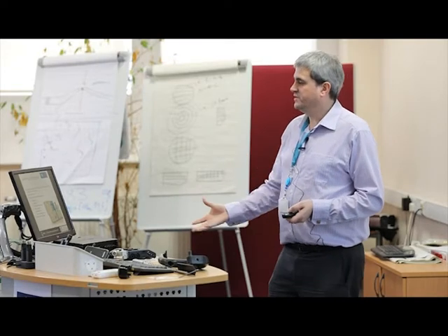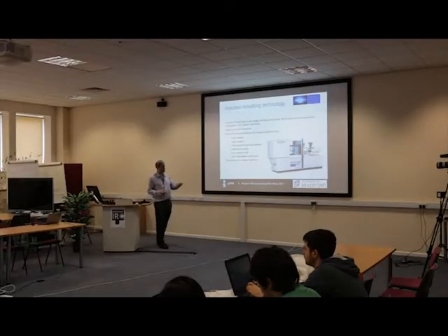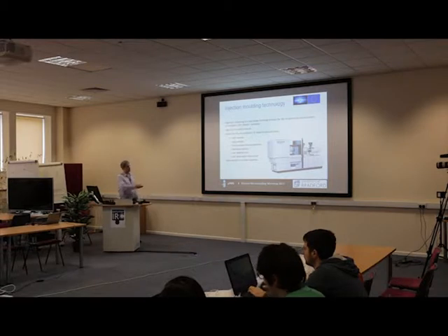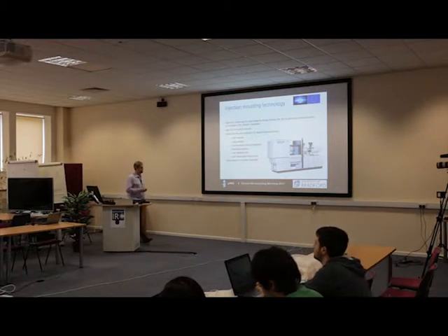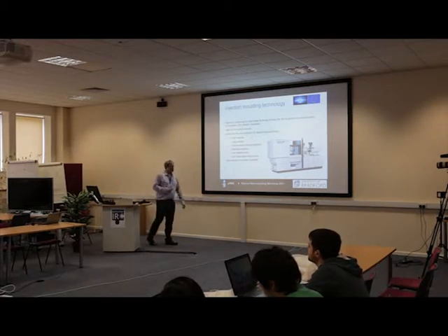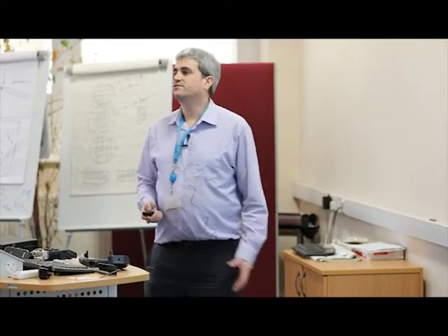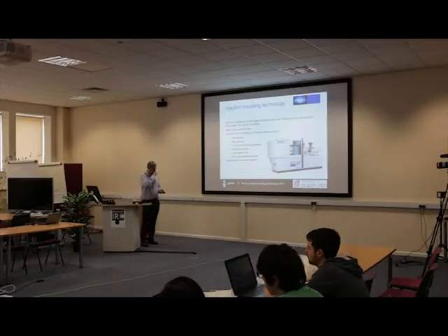In order to form these parts, we're using fairly high forces and pressures, so an injection moulding piece of equipment tends to be a rather large machine to cope with these very high pressures and forces. It needs to be able to handle high stress in the frame of the machine. And as I said before, its reason for existing is to make high volumes of parts at a comparatively low cost using thermoplastics.